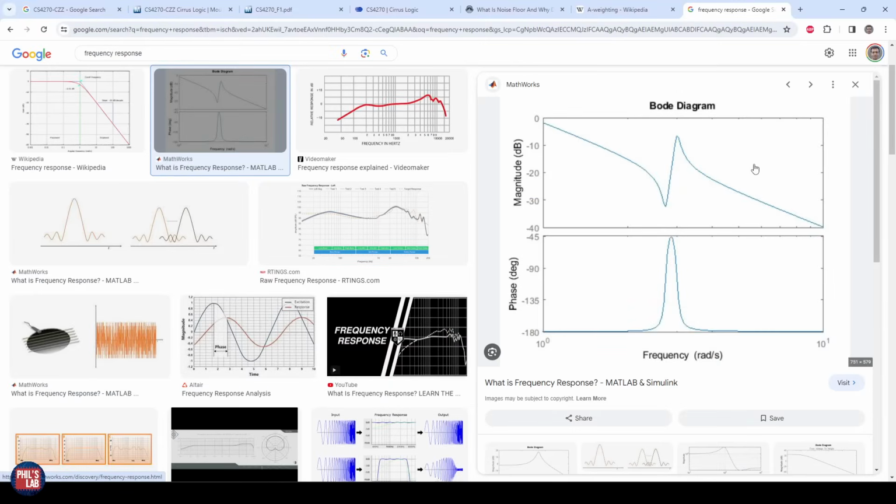Another important measurement is of course that of the frequency response, and this is especially true for audio systems where we might want to have defined lower and upper frequency limits that are only in the audio band, for example 20 to 20 kilohertz, or for equalizers we might want to see how, for example, a control setting changes the boosting or cutting of a particular frequency band, how wide that band is and so on, and we can do that using a frequency response. Predominantly, we are interested in the graph of magnitude, so gain versus frequency, rather than phase versus frequency in this particular audio case.